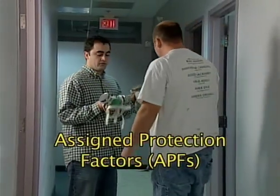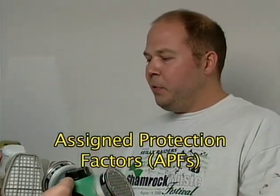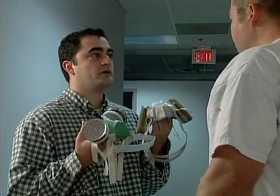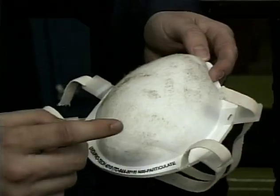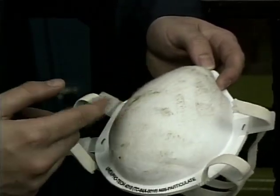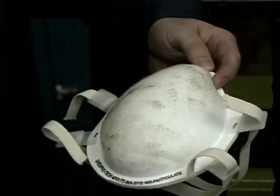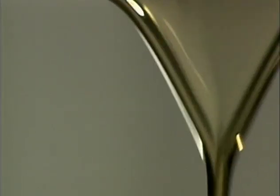OSHA's Assigned Protection Factors, APFs, will help your employer determine what respirator should be used in your work environment. APFs indicate how much protection various types of respirators provide. In most situations, an air filtering respirator is what will be called for. Because oil aerosols can sneak through certain types of filtering systems, NIOSH has created 3 filter classifications based on the amount of oil aerosols present on the work site.